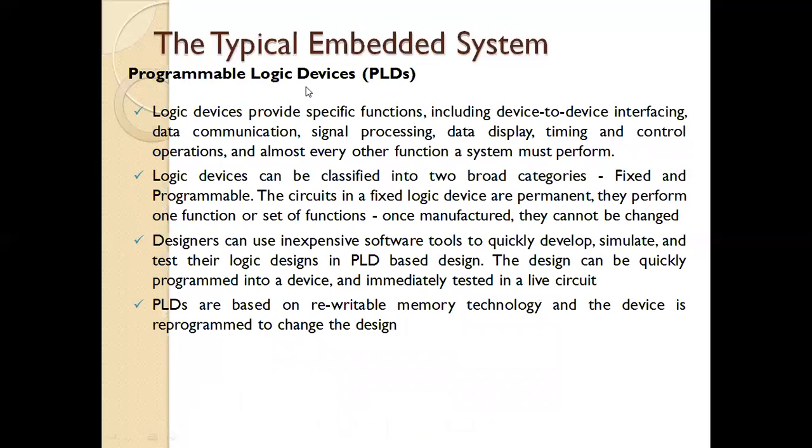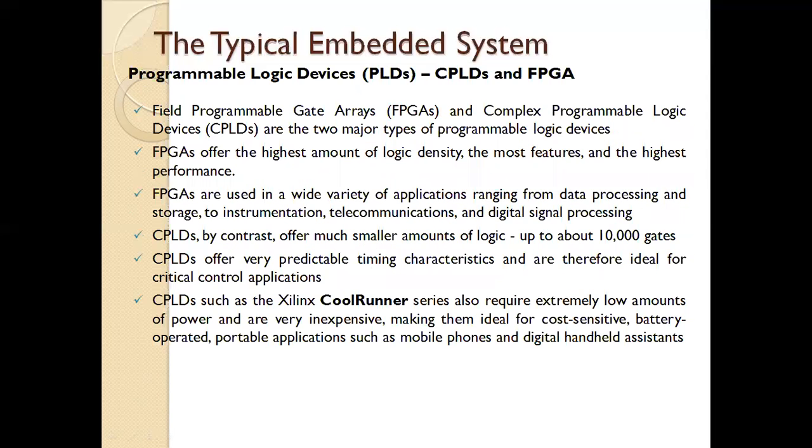Another core element of the system core is programmable logic devices. So already you have seen what logic devices are. Logic devices provide specific functions including device-to-device interfacing, data communication, signal processing, data display, control operations, almost every other function a system must perform. Logic devices can be classified into two broad categories, fixed and programmable. The circuits in a fixed logic device are permanent and they perform one set of functions. PLDs are based on rewritable memory technology and the device is reprogrammed to change the design.